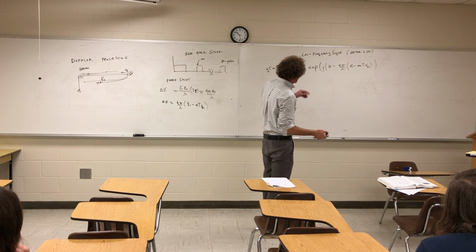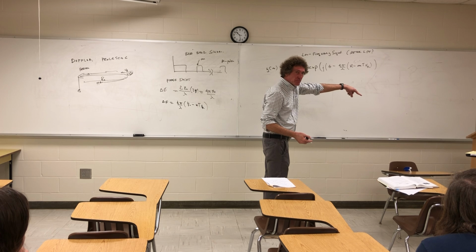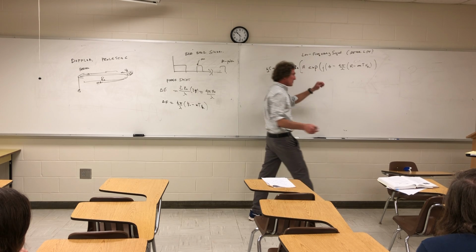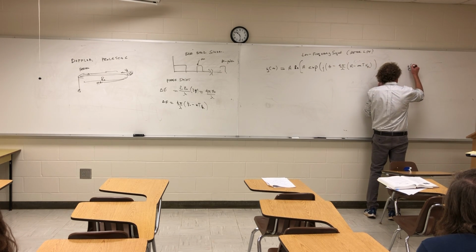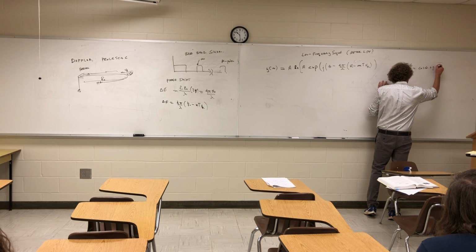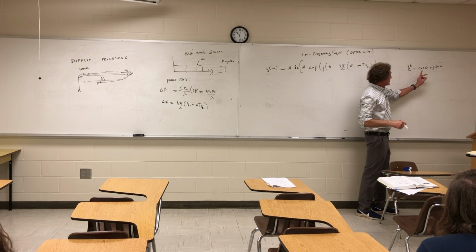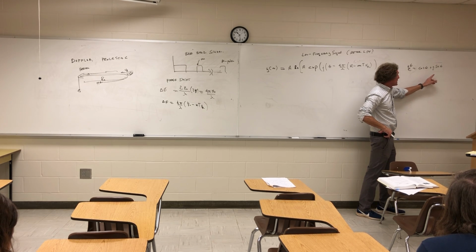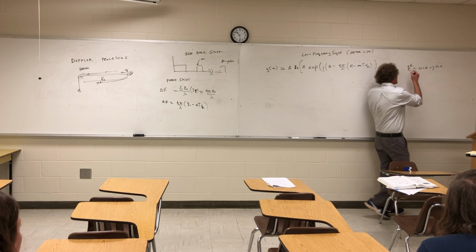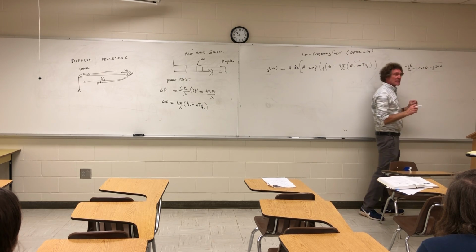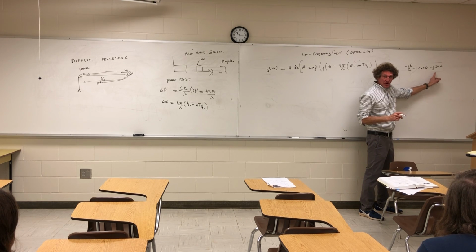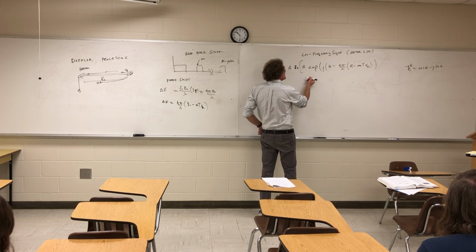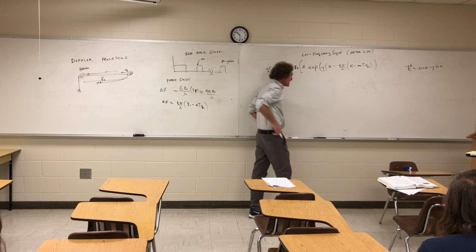What I'm really trying to say is, I had a real and imaginary part coming out of that one, right? I had the cosine, and I had J sine. Well, that is the exponential, isn't it? By that I mean if I have e to the J anything, that's equal to cosine of anything plus J sine of anything, right? Do you remember how there was a cosine here of just effectively 4 pi R0 over lambda? And then this was a minus J sine of 4 pi R0 over lambda. Do you all remember that? Well, isn't that just the exponential? So here I can do this, and actually, I can put the minus on there to make sure it's right.